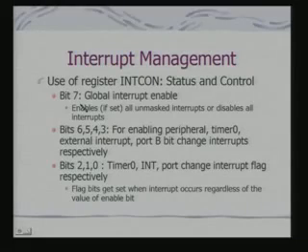I have listed the significance of the bits in the INTCON register. Bit 7 is the most significant bit, because it is the global interrupt enable/disable bit. If we disable this bit, the PIC will not respond to any pending interrupt. Bits 6, 5, 4, 3 are for enabling, respectively, peripheral interrupts, timer 0 interrupts, external interrupt, and port B bit change interrupt.